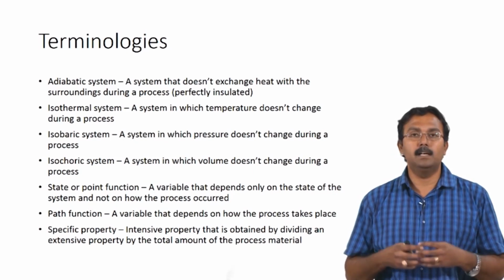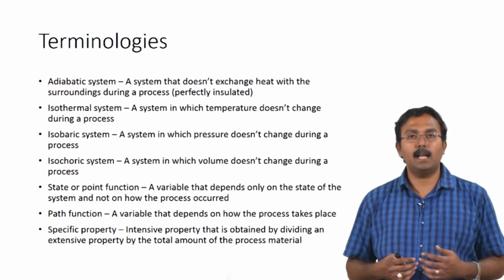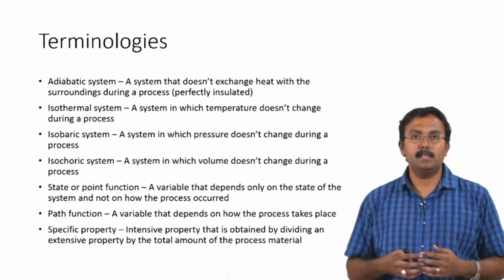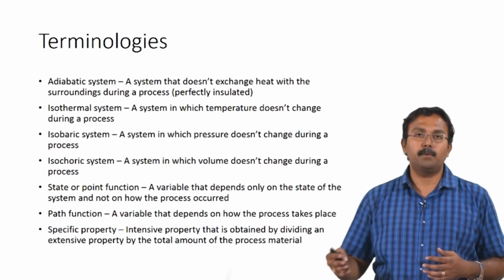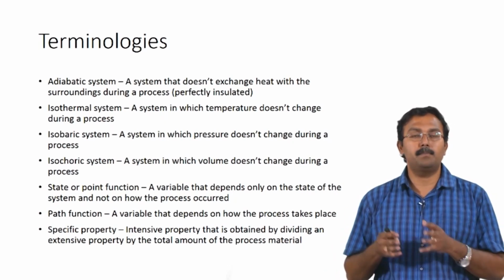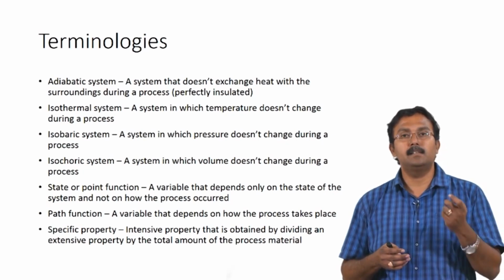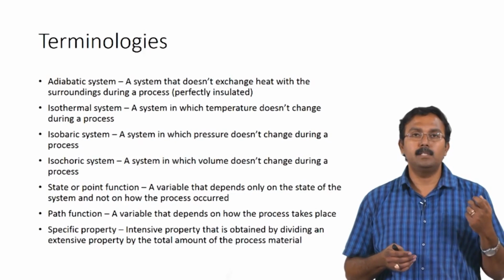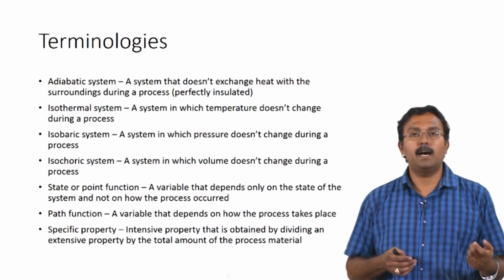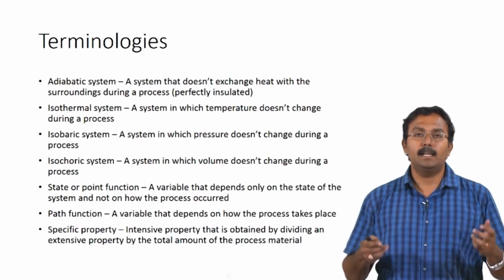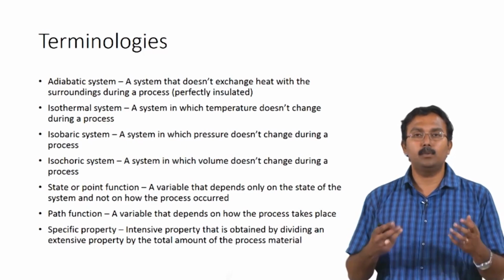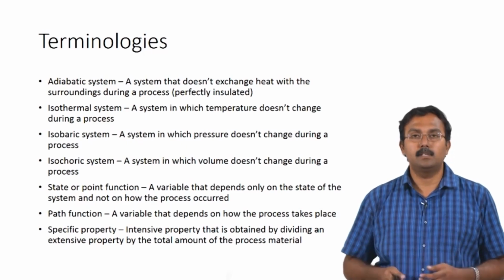Even when we build the internal energy tables and enthalpy tables while performing energy balances, we use specific properties, which are the specific enthalpies and specific internal energies, because we can then multiply that value by the moles or mass of the individual components and calculate the summation to identify the total enthalpy change for the system.